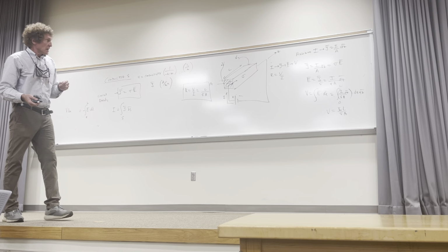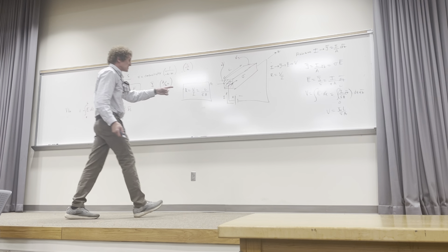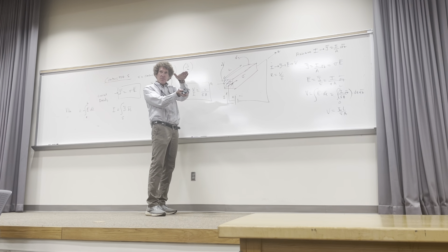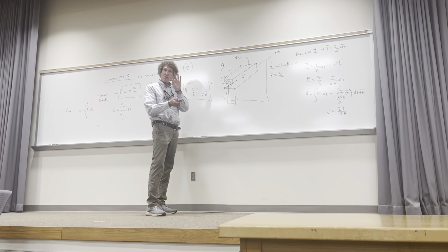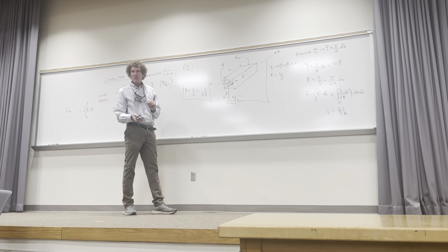Now, that's for the simplest case. That's constant cross-section. You'll note the shape of the cross-section doesn't matter. This could be a wire, circular cross-section. It could be an elliptical shape. It could be a very thin area, right? As long as the cross-section is a constant, and the current density is uniformly spread over it, and that's an assumption, but generally speaking for DC currents, it's guaranteed to be true. That'll be the resistance.